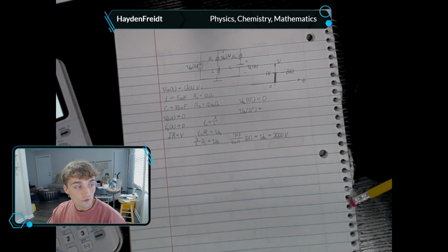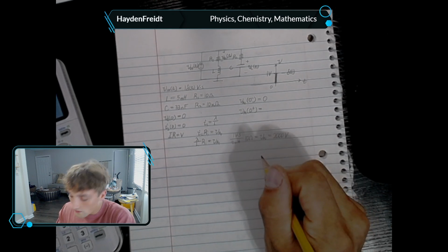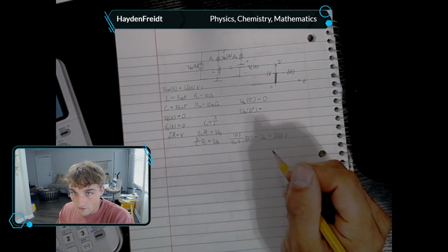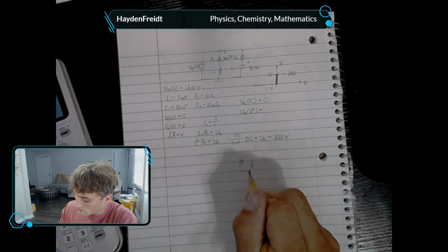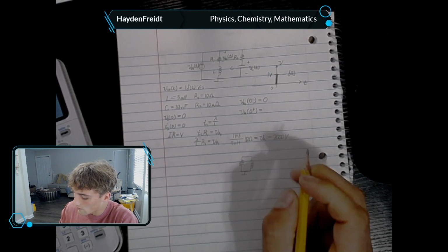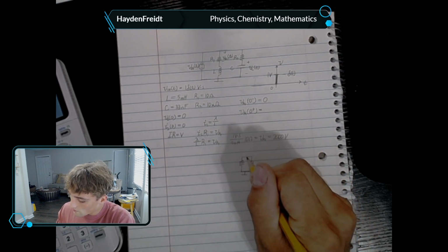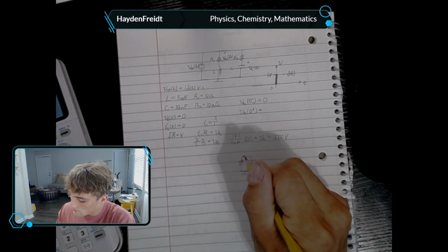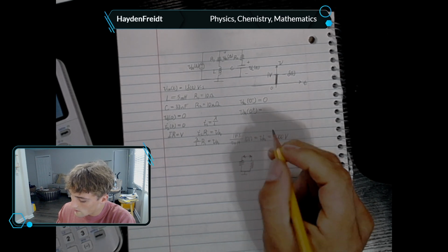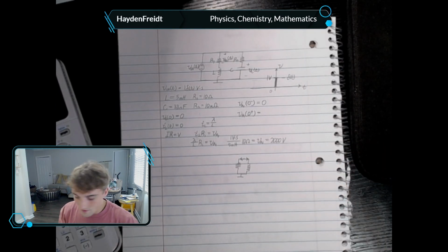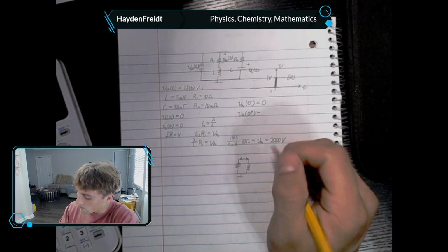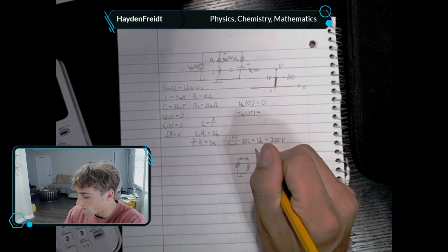What is the value for VR1 of t at t equals 1 millisecond? Okay, so let's draw it in a different model. We're going to simplify it, right? These two branches are decoupled. So we can say that these two elements are in parallel. They share the same current, this way, coming out of this node right here. Let's write down the constitutive law for the inductor.